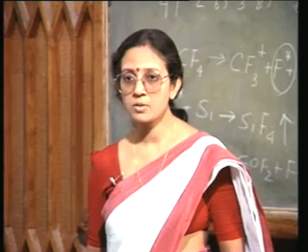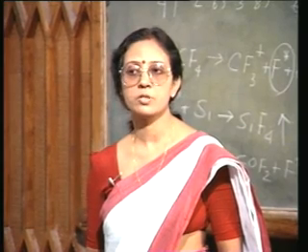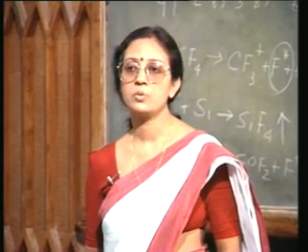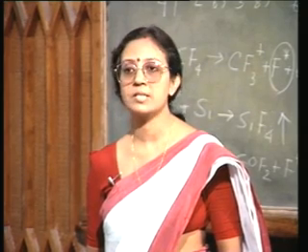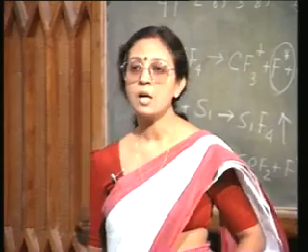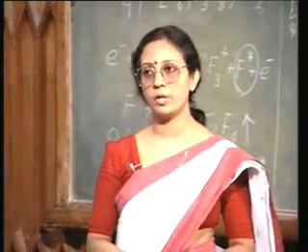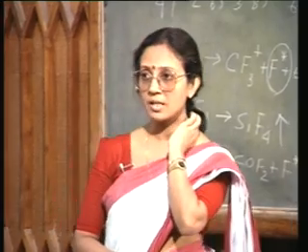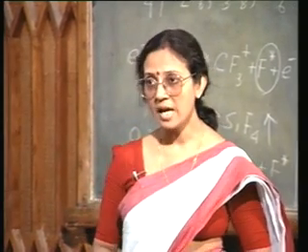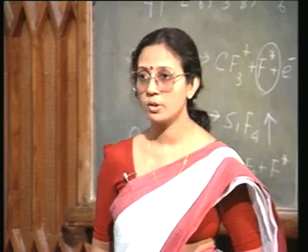So, so long as you have a small quantity of oxygen, everything is fine. You have more generation of fluorine species, which facilitates etching of silicon, but not beyond a certain point, when the silicon surface starts to resemble silicon dioxide, at which time the etch rate is going to decrease.